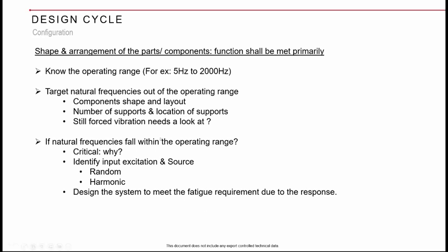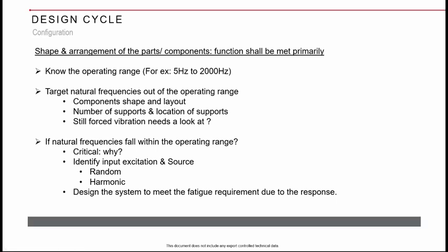So when your natural frequency is within the operating range, you should do a detailed analysis considering the input excitation, either random or harmonic. For those input excitation levels, you should ensure that your system is meeting the fatigue requirements due to the response.